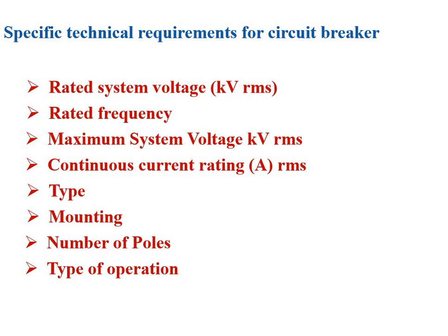In that case simultaneous operation is not possible because the operating mechanism is different for each circuit breaker. But if it is a 4-pole circuit breaker, then you can go for simultaneous operation. So you also have to decide which type of operation you require.